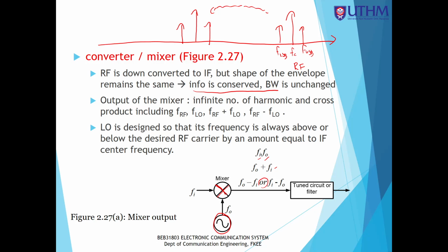So in my example here, I have three components, 1, 2, 3, of RF frequencies. That means the mixer will down convert all of these into the intermediate frequency, which is FIF center. USF, upper side frequency, or you can say upper side band, is similar.